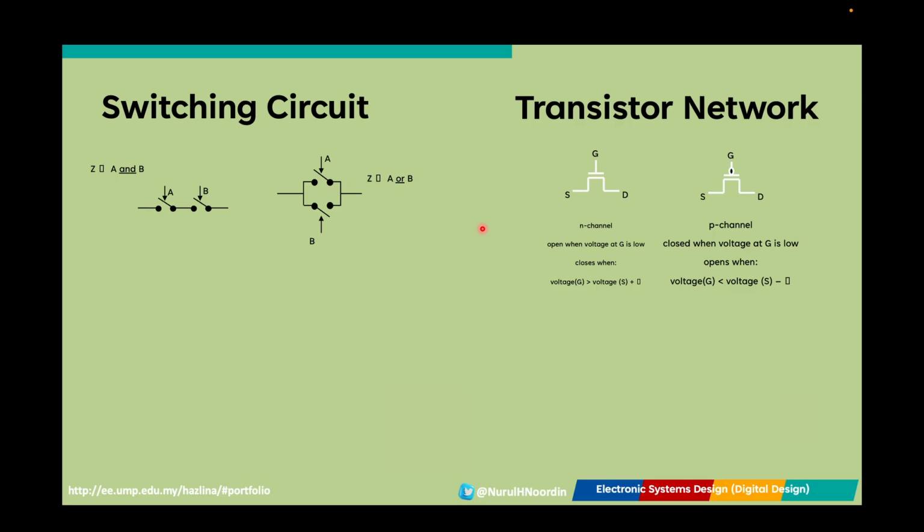If the voltage at the gate terminal is higher or lower than the source terminal, then a conducting path will be established between the drain and the source terminal. An example of a switch is shown here. So, when a 1 is placed at X, the N-channel MOS is closed, hence giving the output of 0. This function resembles the inverter.